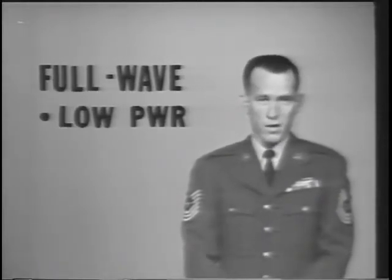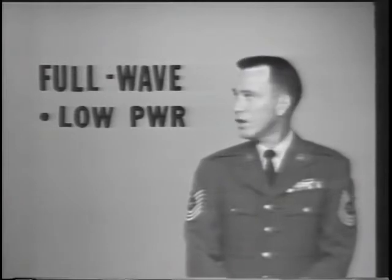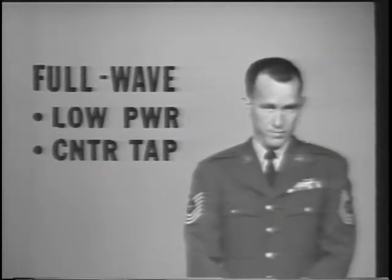Even the full-wave rectifier has its limitations. Though able to supply more current to the external circuit than the half-wave, it is still a relatively low power device. And because it requires a center-tap transformer, only half the available secondary voltage is felt in the output.